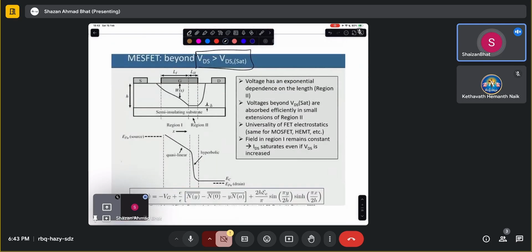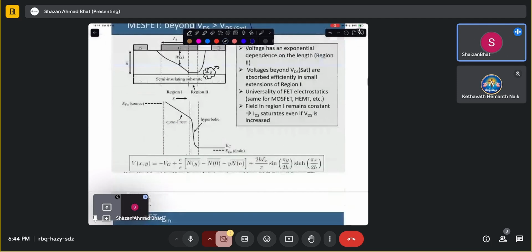What happens in this region is that you have that delta I was talking about, a small region which remains via which the current can flow and the electrons can flow at saturation velocity. This is the region I talked about. The electrons here can go down the hill with almost a velocity equal to saturation velocity. And now you have certain equations, and it doesn't matter how this equation comes up, you just have to solve something called the Poisson equation.